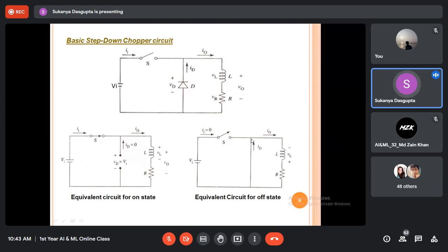And when the diode is conducting, if you consider an ideal diode, there will be no voltage drop across the diode. So this part containing the diode will be like short circuited. Whenever the diode is conducting, if it's an ideal diode, it will be a short circuited part. Right? The voltage drop across the diode during the conduction mode will be equal to zero. So zero voltage means a short circuit. So current will be flowing. Whatever energy is stored within the inductor will be totally dissipated through this path.